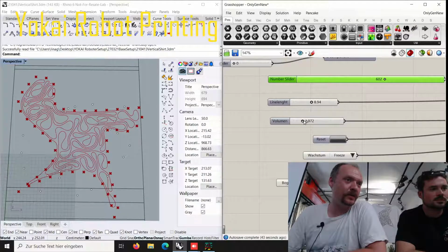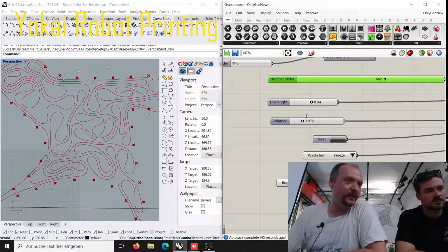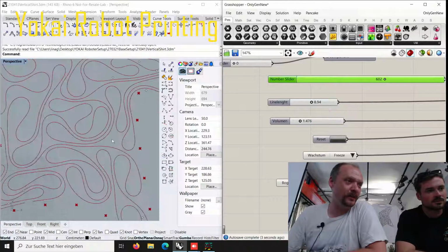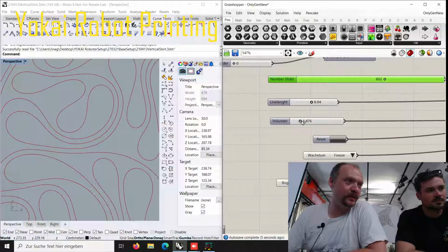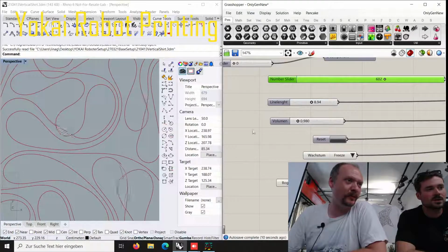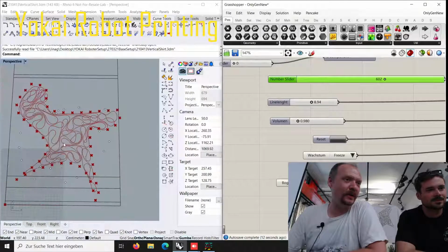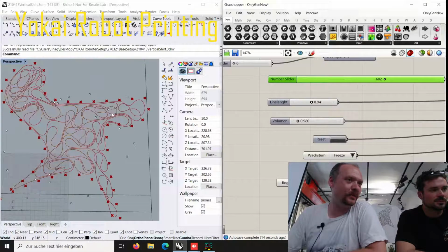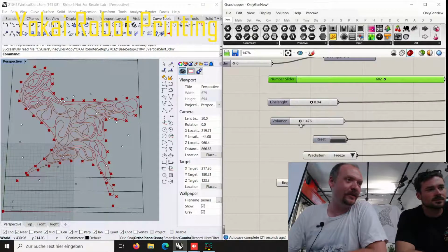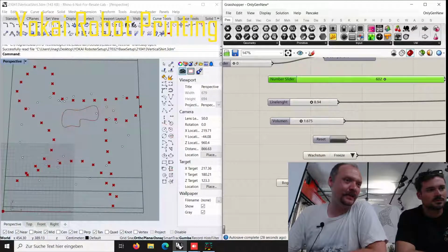I can also change the distance between the lines. It's 1.9 millimeters now. I can bring it down. When you look closely, you see the distance between these lines is changing. Now it's even overlapping. I went a little too far maybe. But anyway, when such a generative part gets out of hand, you can restart it, and then it will be generated again. So let's reset it once.